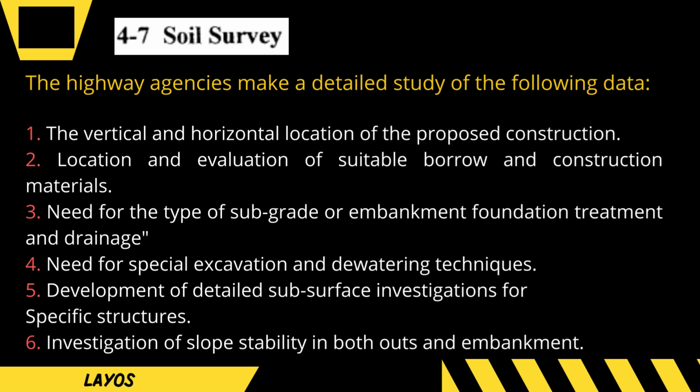Fourth is the need for special excavation and dewatering techniques. There are 4 main dewatering methods used in construction. First is a well point, eductor wells, sump pumping, and deep well point. Fifth is the development of detailed subsurface investigation for specific structure. And the last is the investigation of slope stability in both cuts and embankment.